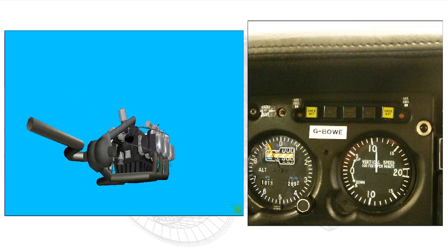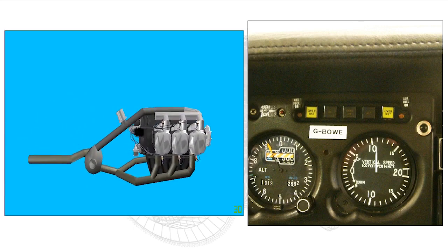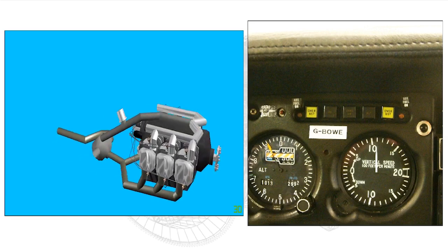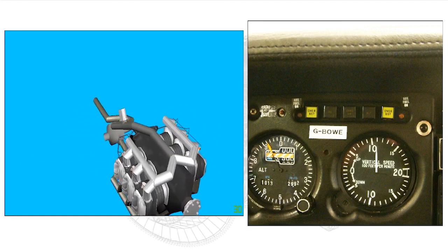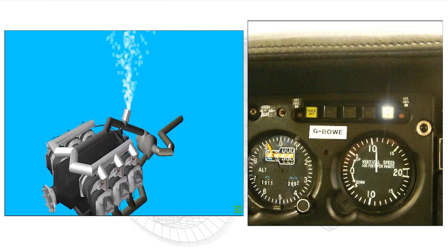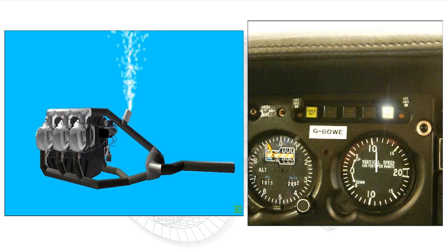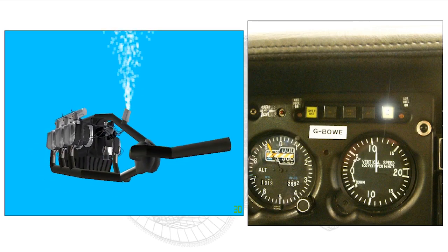Additional safety features may be built into some systems. These can take the form of overboost warning lights and an overboost relief valve. If, despite the overboost warning light, the maximum boost is exceeded, then the overboost relief valve will open and relieve compressor outlet pressure to atmosphere.